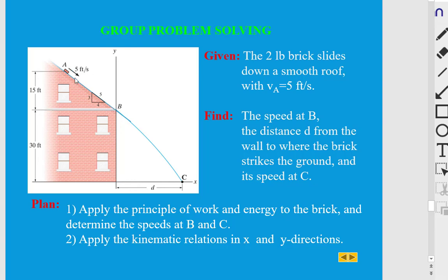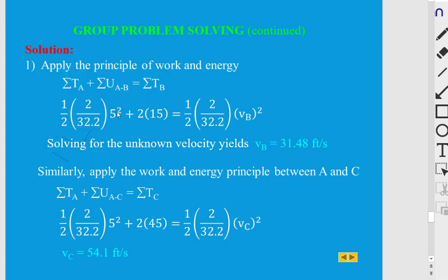so it's gaining velocity in favor of T2. So we expect that this has to be added to the T1 plus the amount of energy gained by the weight, or the work done by the weight, which is simply the weight times delta y. Weight is 2 multiplied by delta y. From here to here is 15, which is already given to us. So 2 by 15. So we have one equation we can solve for VB. So let's take a look at the details.